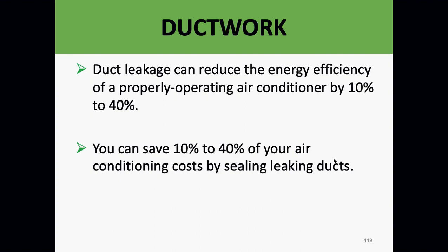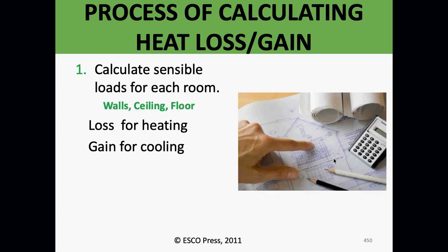And ductwork sealing does not last forever. In other words, whoever installed it 15 years ago may have sealed the ductwork perfectly, but as things settle, as things heat and cool and move, the sealant breaks down after a while. It does fall apart. Important to take a look at.